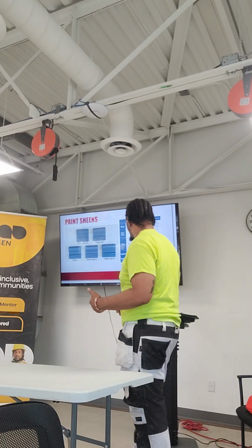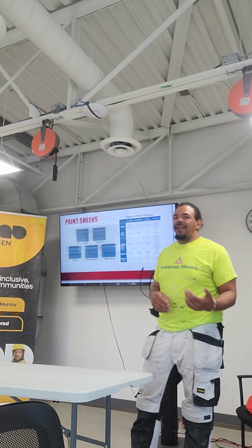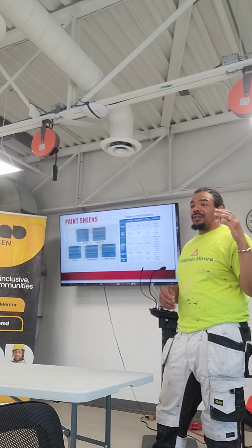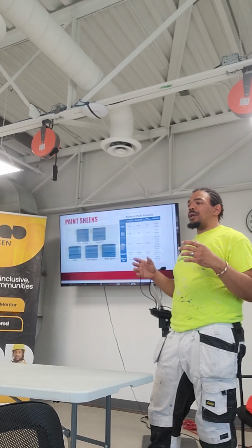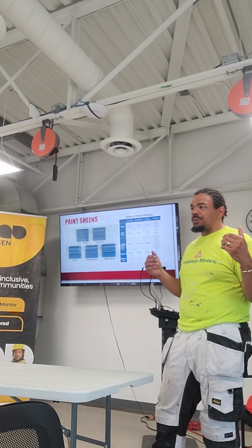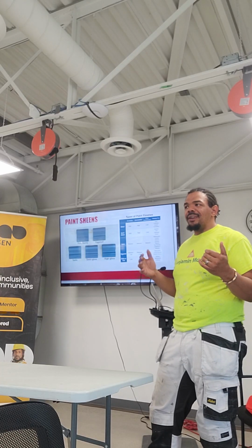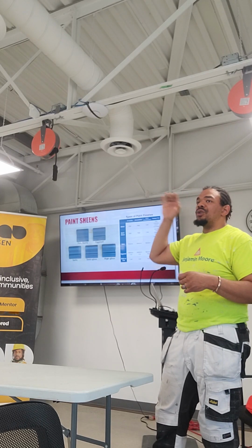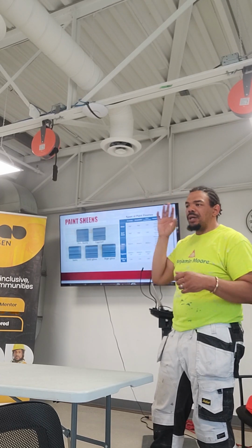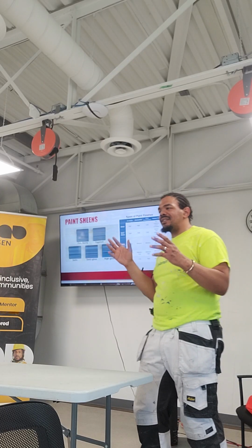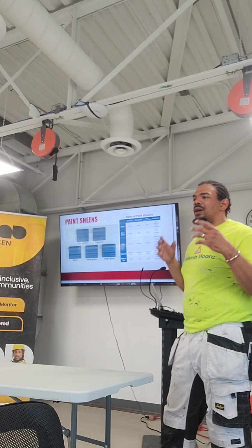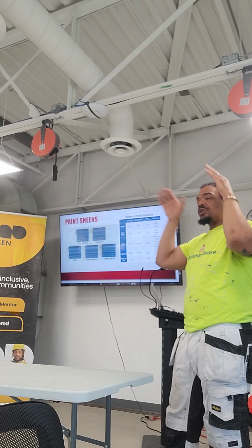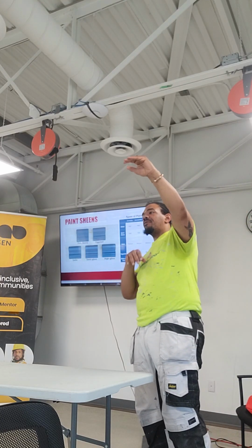And then, of course, your matte and your flat. Now, matte and flat paint is what you see traditionally on ceilings. And they put flat paint on ceilings really because a lot of people who do ceiling work and who build houses and who tape and finish ceilings with mud, the ceilings can be done poorly. So if you were to put a semi-gloss or satin paint on a poorly finished ceiling, you're going to see all of the tape joints, you're going to see all of the mud problems, you're going to see all of the areas they didn't sand correctly. So it'll be a lot more unsightly because it'll show more of the imperfection because the sheen level is so high. So to prevent that from becoming a major issue, people use flat paint.